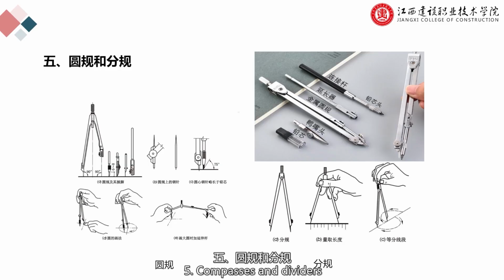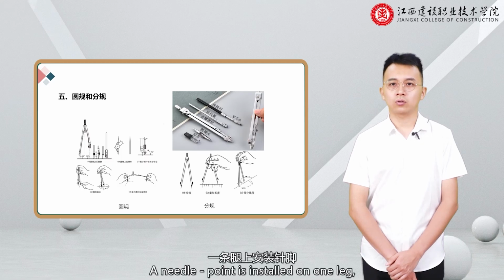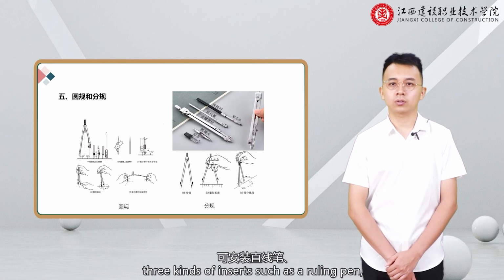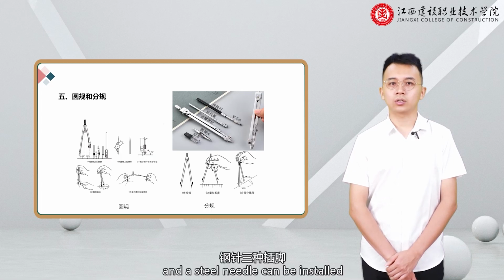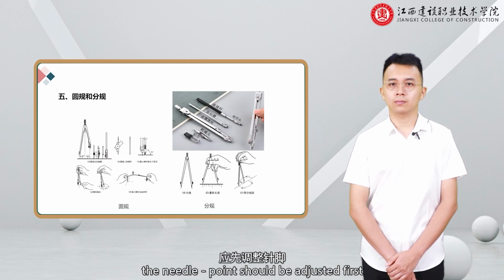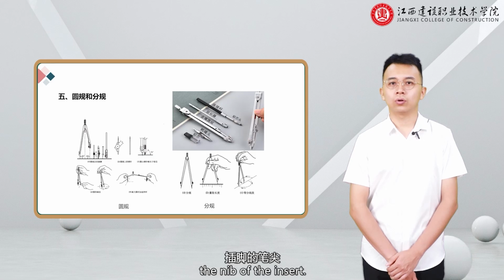Fifth, compasses and dividers. Compasses are tools for drawing circles and arcs. A needle point is installed on one leg, and on the other leg, 3 kinds of inserts such as a ruling pen, a lead core, and a steel needle can be installed. Before using the compasses, the needle point should be adjusted first, so that the needle tip is slightly longer than the nib of the insert.